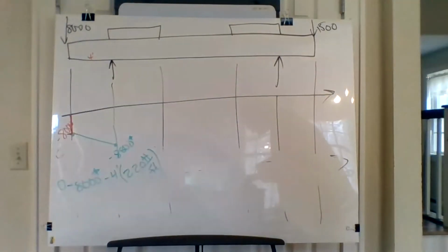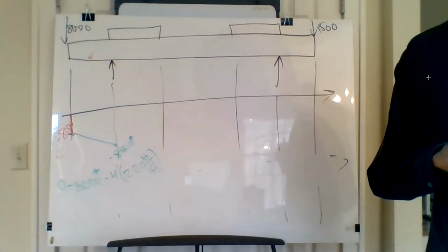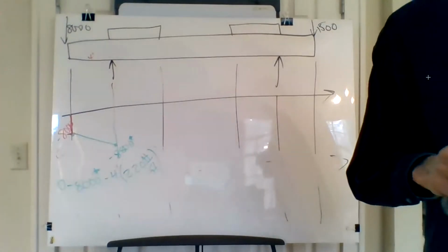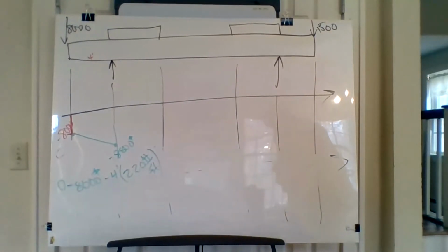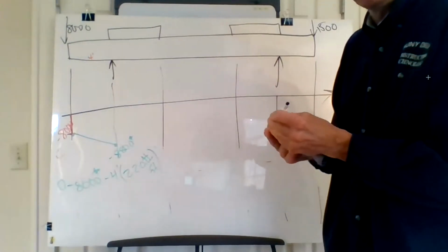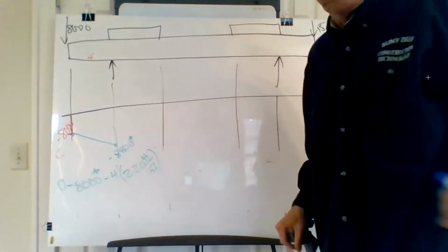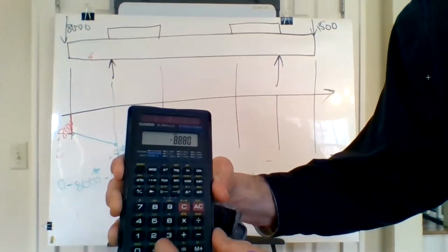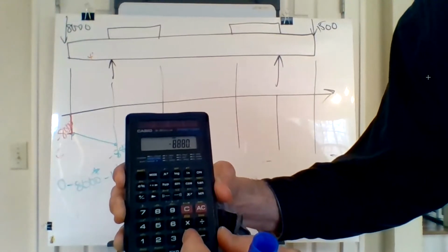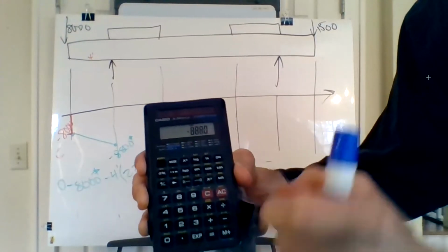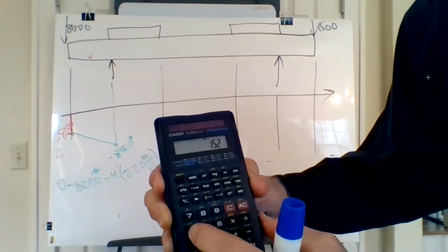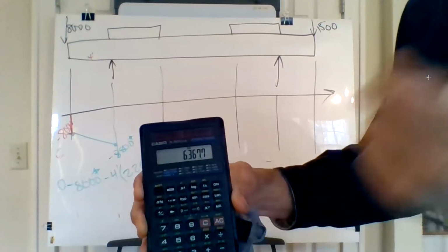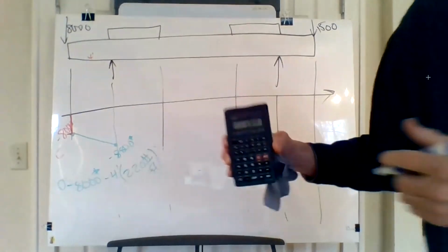Now what do I do? Bueller, anybody? Now you have R1 going up, right? The cantilever. So I take whatever that value was, I leave that right in my calculator, and I'm going to add, if I can find the plus button, 15,247.7, and that's the value of the shear curve right here.